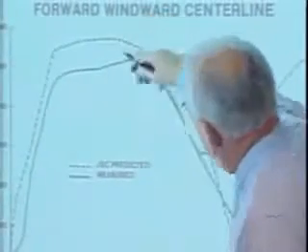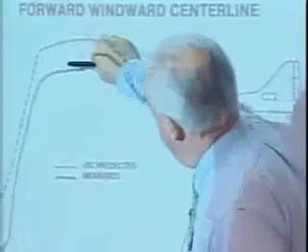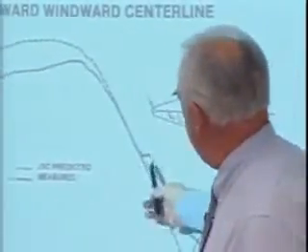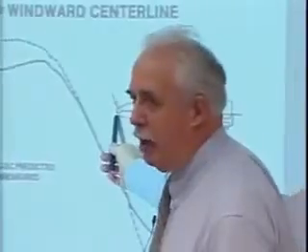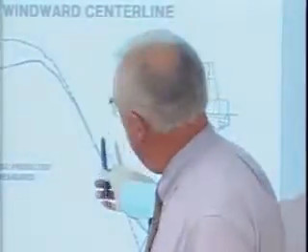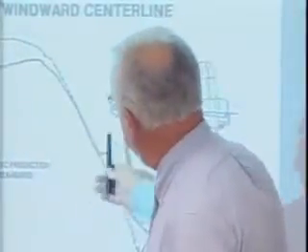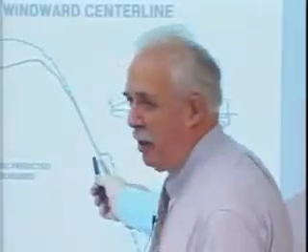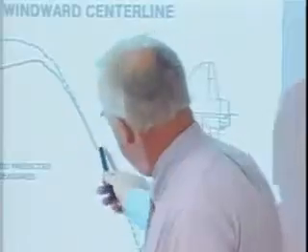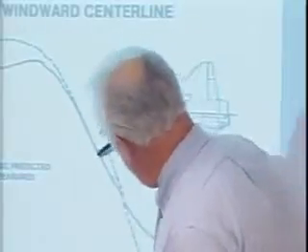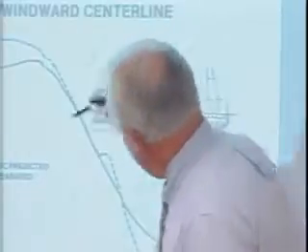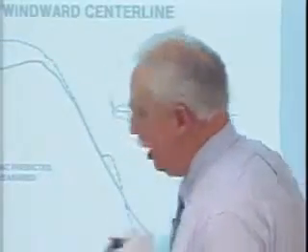Now over here, what happens is I try to stay laminar. I come down, and we predicted well, this was really a stretch. We never got turbulent heating up on the nose, okay? Way beyond wind tunnel, way beyond our experience base, but the model just went up there. So we really didn't expect that. That was a pretty conservative boundary layer transition. And then, well, son of a gun, the actual temperature is higher than turbulent, even though it would appear to be laminar.